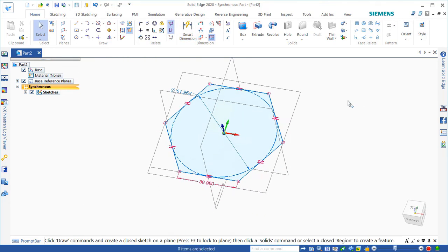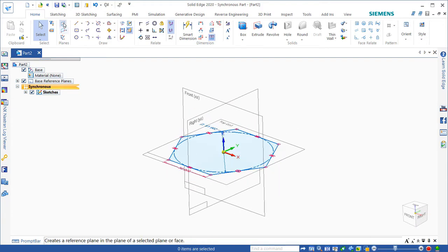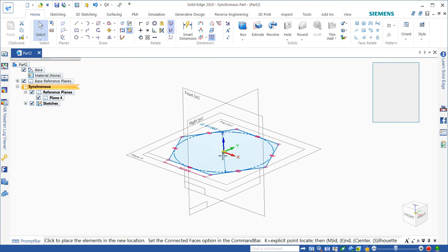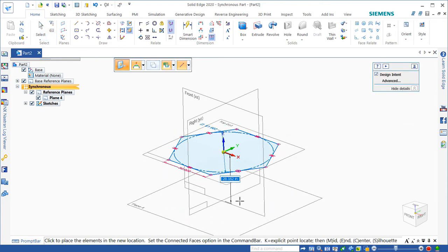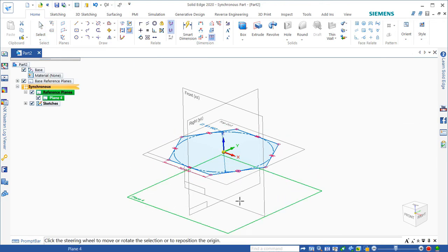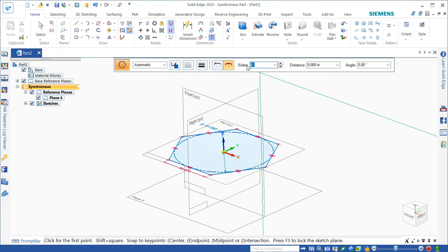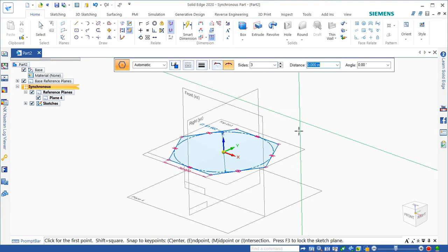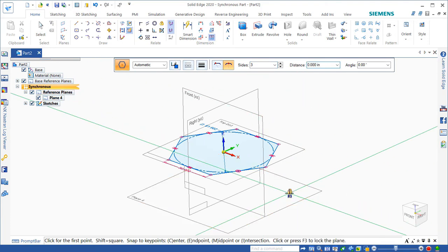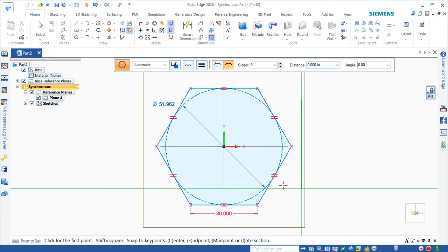If you noticed in the picture, it's 3-sided on the bottom. It's a triangle. So we'll just offset this plane. I don't know exactly where this needs to be, so I'm just going to guess with 24 inches. Alright, and then what we're going to do is run the polygon command again and lock to the bottom face. This is going to be a 3-sided. So we'll lock onto that face, go to a top view.